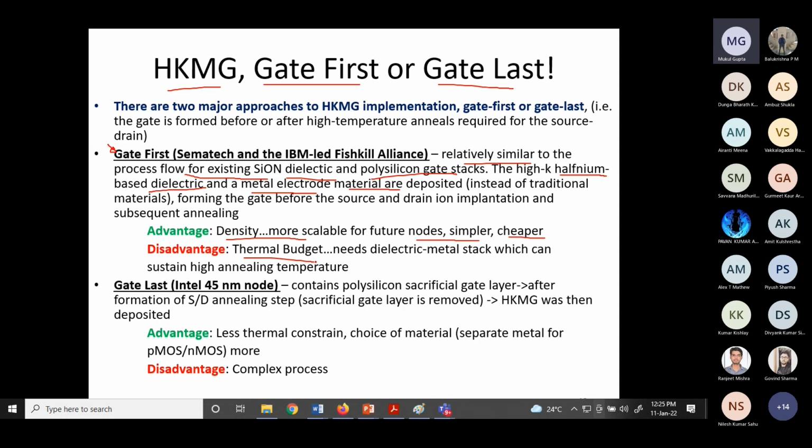Then on top of that they deposit polysilicon. Now if you deposit polysilicon, you remember you have a thin depletion layer in the polysilicon oxide interface. But they didn't use polysilicon as a gate contact. They use polysilicon gate as a masking layer and create the source and drain, anneal everything, all these processes they have done. Then they remove polysilicon, okay.